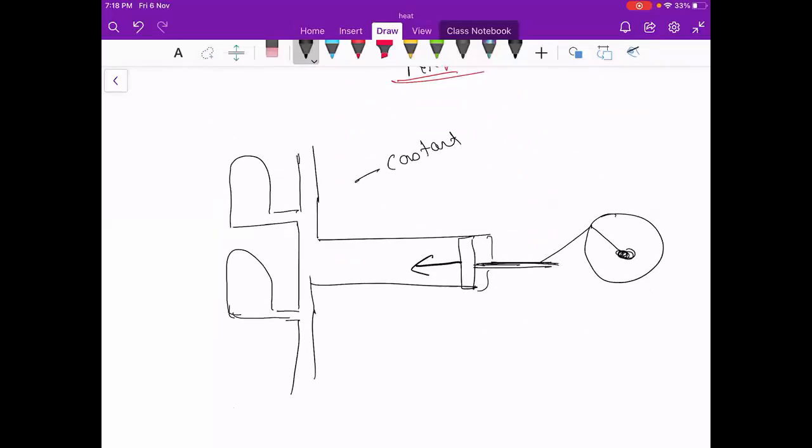So see what will happen. To reduce the fluctuation in our system, we will fill this chamber with pressurized air. So what will happen when the piston comes to this position? The fluid has more density, so some fluid will go in this direction and some will be here. It will compress the air in the system. But when the piston is coming back, what will it do?